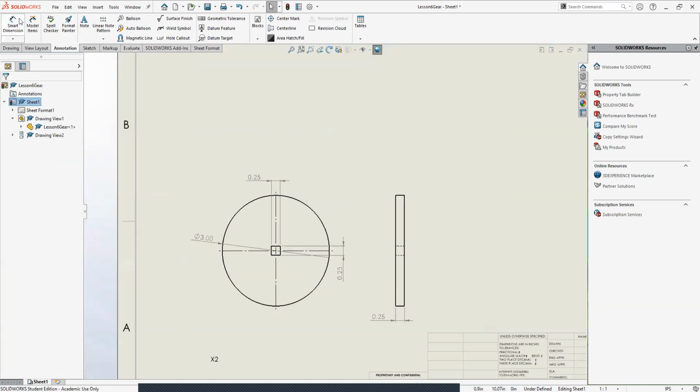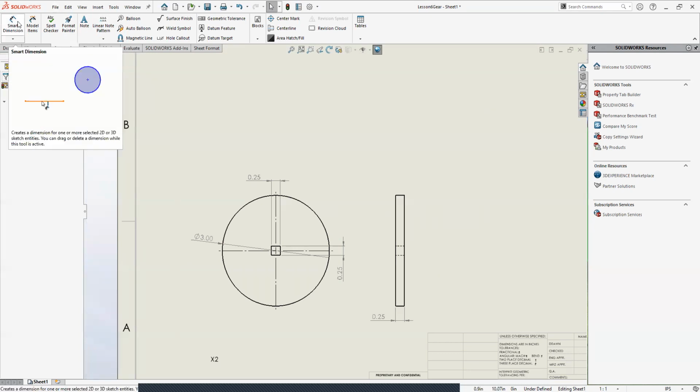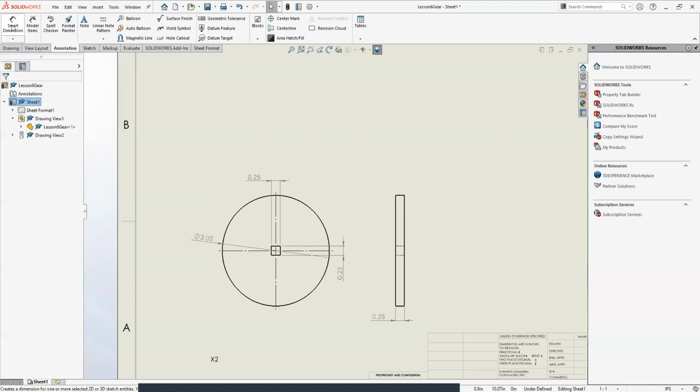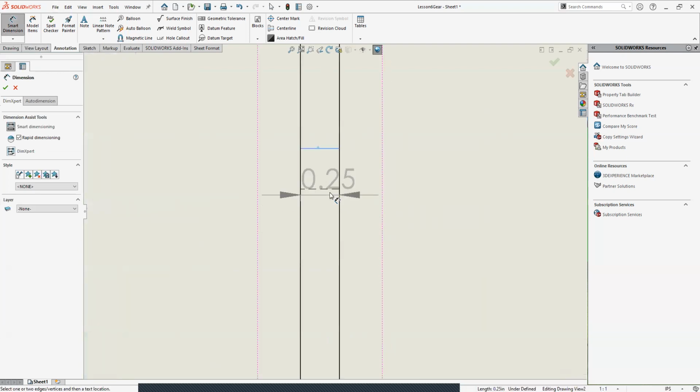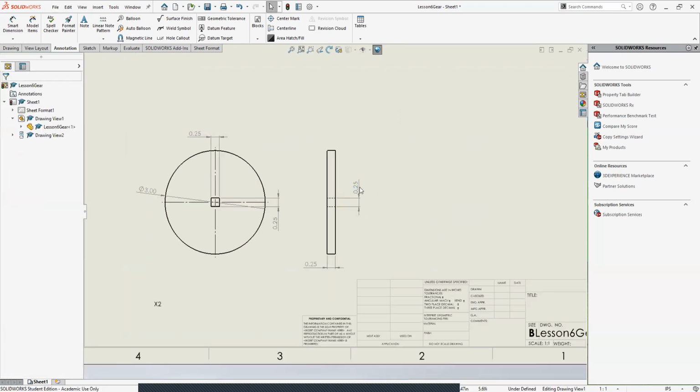So a couple other rules when you're doing drawings. I'm basically going to break a rule. So we'll just do something real quick. Remember how we did hidden lines on this view? What I have just done is added a dimension to the hidden lines. Like I've used the hidden lines to make a dimension, right? Never ever do that.